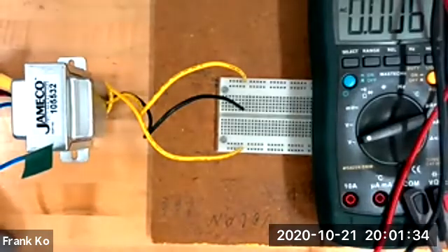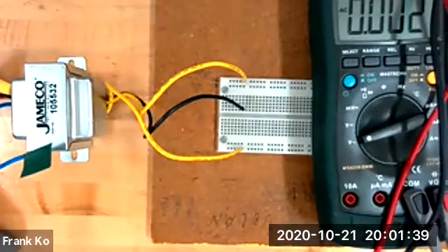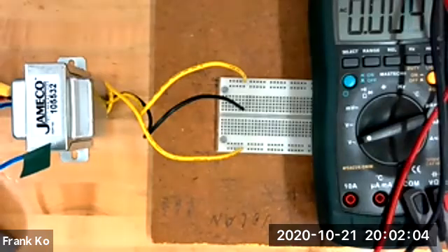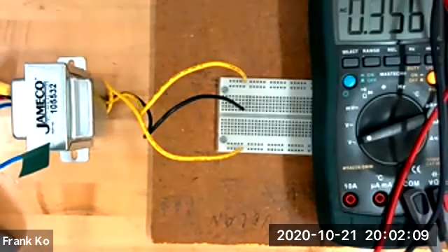So, what to do? Before I have you plug things in, can you all check each other and make sure the two secondary wires are not on the same rail? Look at your classmates. Don't look at yours. Look at each other's. Make sure we're not shorting those secondary wires. Do you agree your classmate has it connected separately? Flying colors. Okay. Then and only then, plug in the power cord to a receptacle.